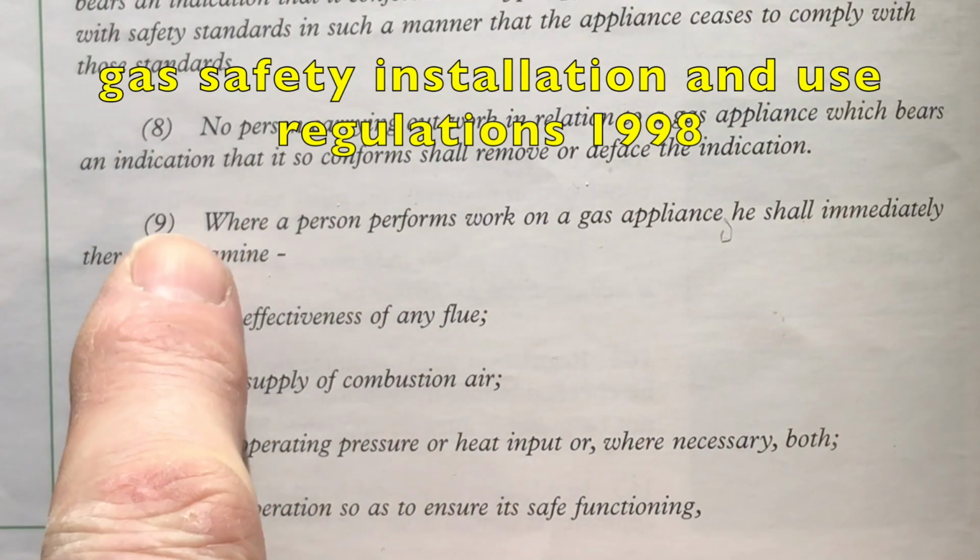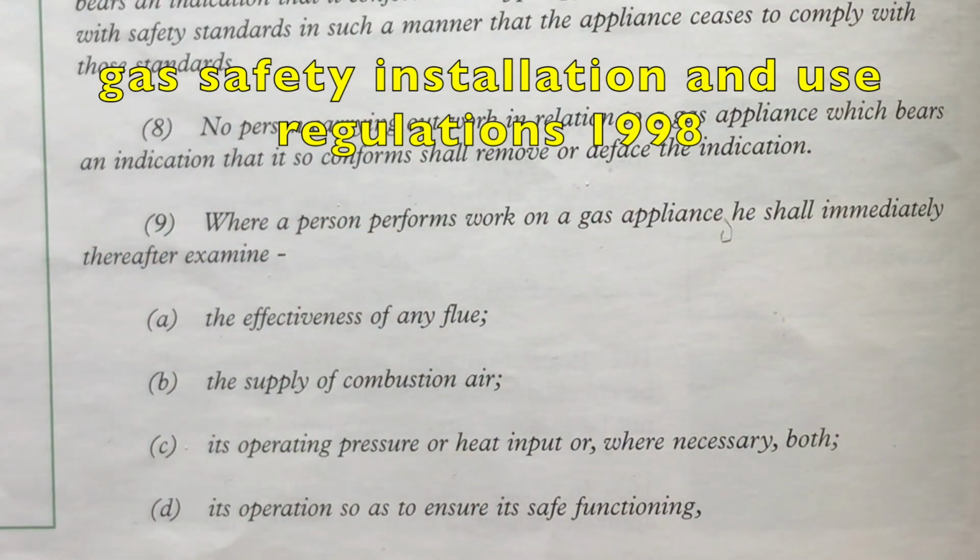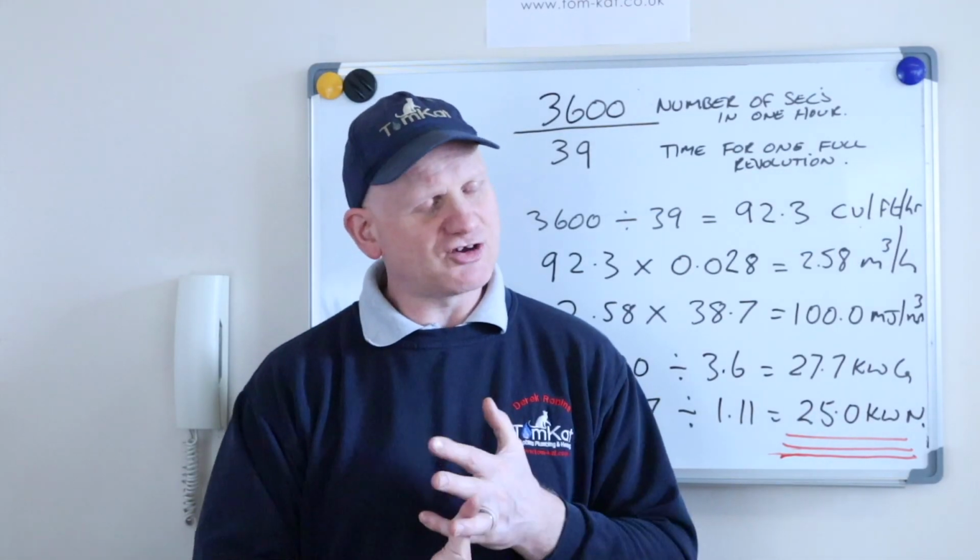So remember, gas rating is a part of regulation 26.9. So this here is regulation 26.9. So where a person performs work on a gas appliance, he, she shall immediately thereafter examine the effectiveness of any flue, the supply of combustion air, its operating pressure or heat input, or where necessary both, and its operation so as to ensure its safe functioning and it's not affected by any other appliance. So that's what we're checking according to regulation 26.9 every time we do some work on a gas appliance. So that's gas rating of G4, gas rating of U6.